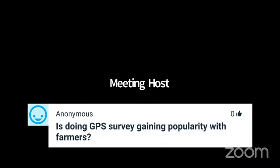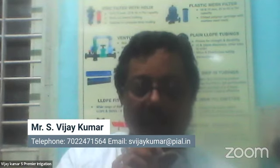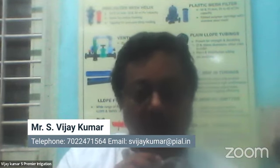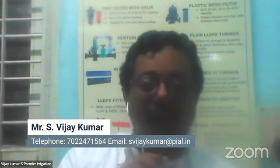Is doing a GPS survey gaining popularity with farmers? Yeah, GPS survey has become the in thing today. Like I showed you in the last slide, even though they may not be in a position to buy an instrument, most farmers have started using the apps that are available in the Play Store. They are fairly accurate, 90% accurate. But when irrigation companies like Premier Irrigation carry out these surveys with a GPS instrument, we need a fairly accurate dimension, and we can have the elevation also, so that our pipeline design and hydraulics are taken care of properly.